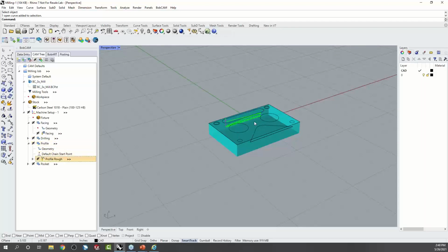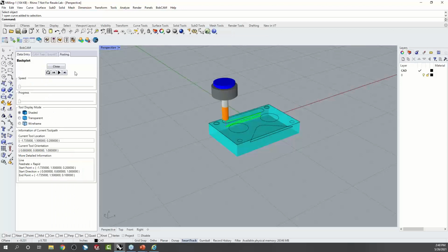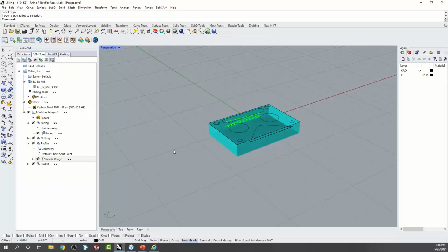This is profiles. It's very, very common to work with profiles. In this example, I have this doing contour ramping. This allows you to ramp down as you cut. I use this in all kinds of 2D and 3D routines, ramping around profiles to remove materials, clearing out bosses, a lot of different options in here.